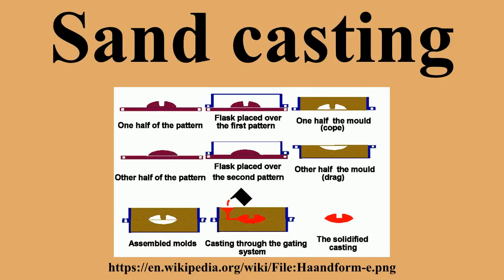Gas pockets can cause internal voids. These may not be immediately visible and may only be revealed after extensive machining has been performed. For critical applications, or where the cost of wasted effort is a factor, non-destructive testing methods may be applied before further work is performed.